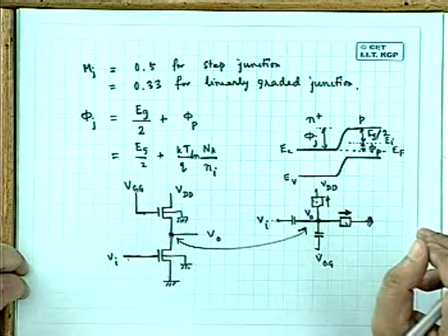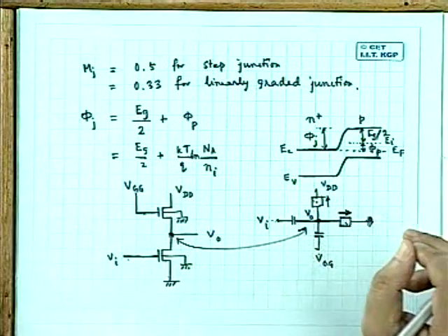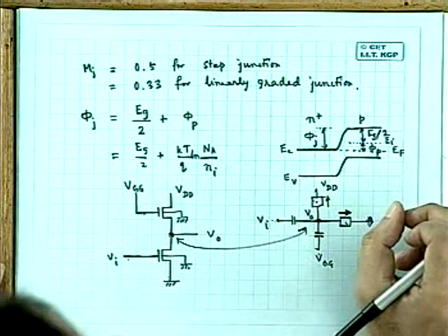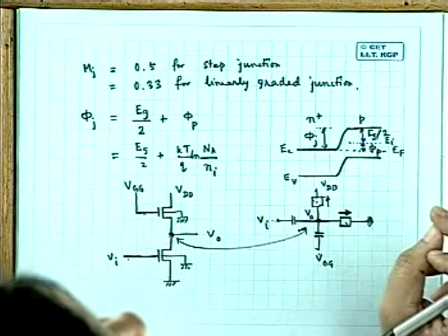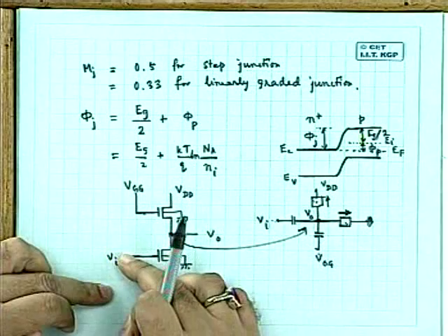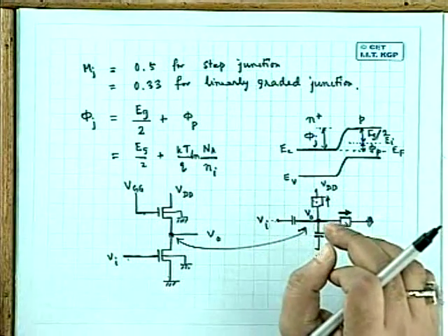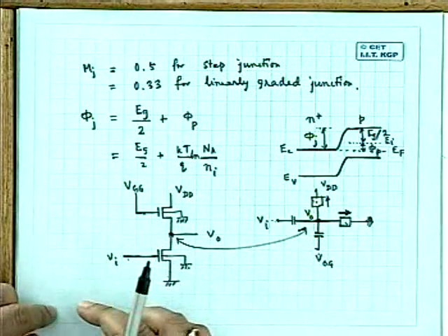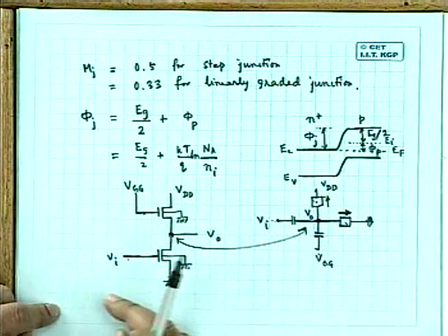So what you have to do, as I have indicated earlier, is discretize in the time domain. You have to start with some trial variations which are obtained from DC analysis. If you change the input voltage from 0 to Vi, I know how all these voltages and currents change. Suppose it is a linear thing, slowly, as I am changing time from 0 to say 5 seconds or 100 seconds, then this is how.